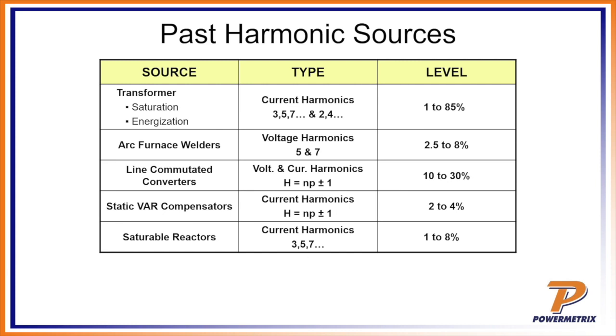I have a real good story. Once upon a time I had a customer call me up, had a Powermaster system, I was testing out in the field and was having a problem. He called me up and said, "Hey Steve, I've got a Powermaster 7 series. I've been trying to run some tests on this thing, but this thing just won't power on." I said, "Well, Mr. Customer, tell me something about your site." He's like, "Well, I'm out at this site, it's a 9S site." I said, "Okay, 9S, transformer rated. Tell me, first of all, do you have PTs on the site?"